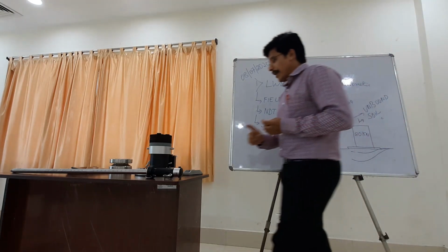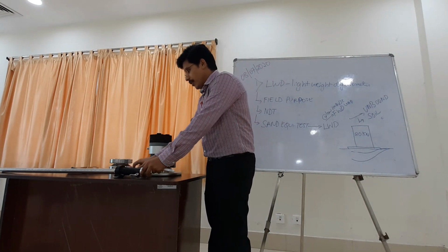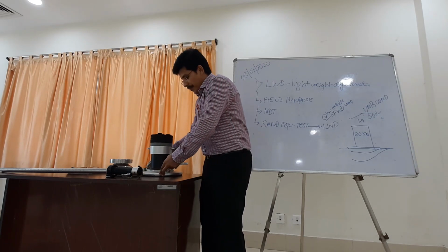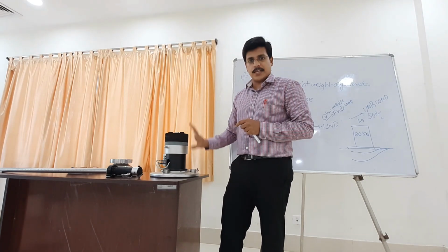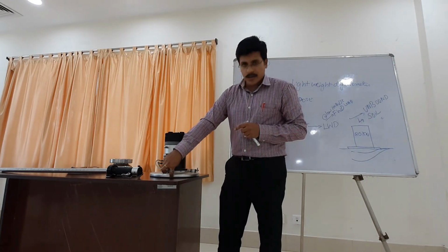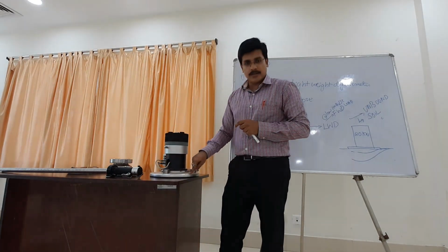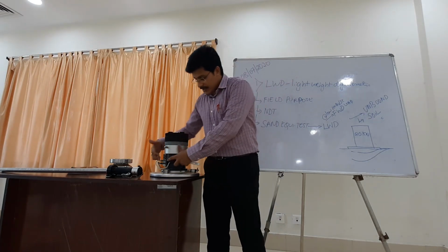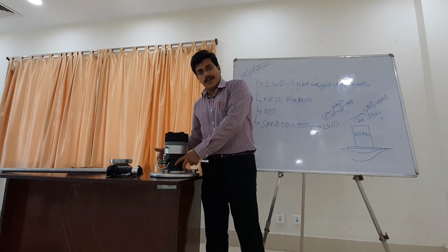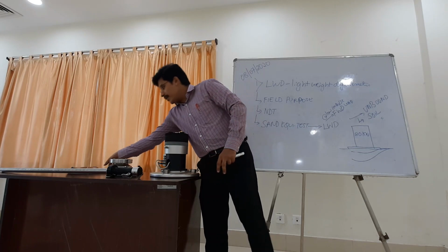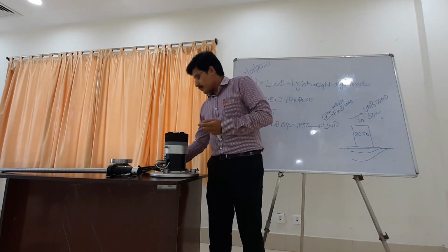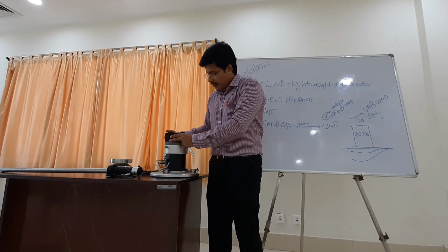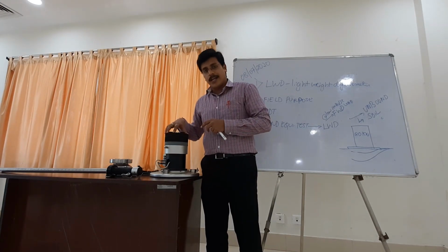So moving to the equipment, now we have different components here. Now this is basically the loading assembly, complete loading setup. We have a rubber pad here, right? And then we have a loading plate. And then we have this load cell arrangement, and also it has a communication device to communicate the data with this tablet, right? And then this is the buffer ring. The buffer rings are used to control the time of contact.